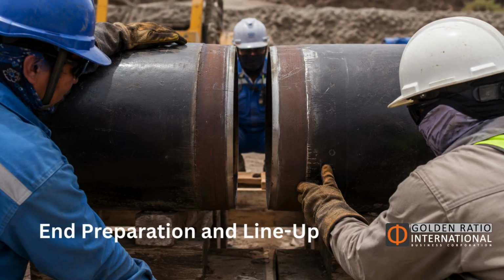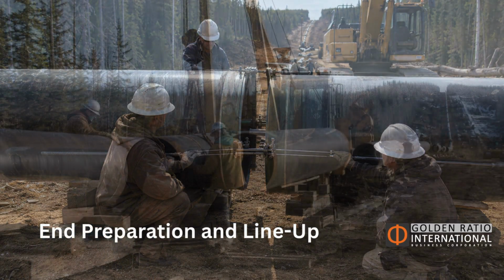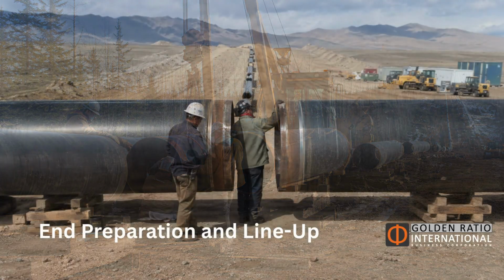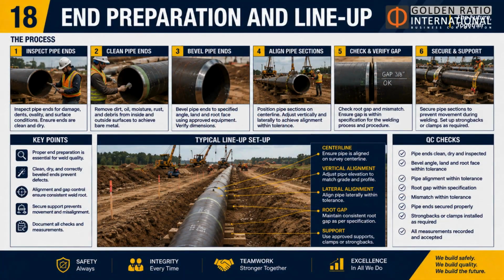This stage may look simple, but it has a major influence on welding productivity and quality. If end preparation is poor, weld rejection can increase, and if line-up is slow, the welding crew loses time. End preparation and line-up turn individual pipe joints into a ready-to-weld pipeline string.